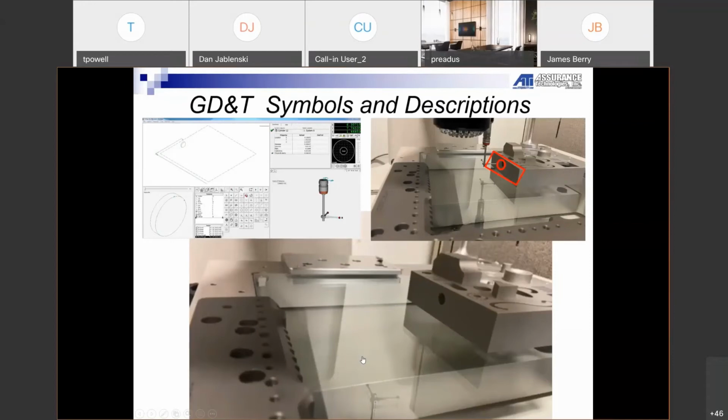One thing that I want to mention with the star probe is you see in the top left corner picture that I have there, you see the styli B is highlighted. I still forget to click sometimes if I'm using that styli. You need to tell Inspect which styli side of that star probe that you're using, so it knows where it's triggering off on, and put that in there. Very common mistake. I still forget sometimes when I'm programming and have to go back. So it's just a little tip there.